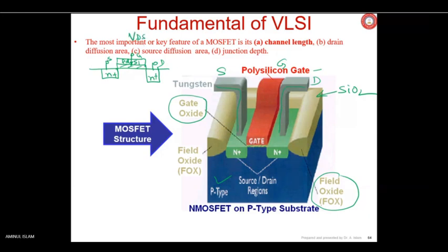VDS, negative terminal here, positive terminal here. VDS. Okay. If you apply this voltage, if this voltage is larger, what will happen to depletion layer? See, here you have no bias there. Yes, you have grounded it, substrate or p-type body or substrate is connected to the ground or zero potential. Your source is also connected to ground or zero potential.